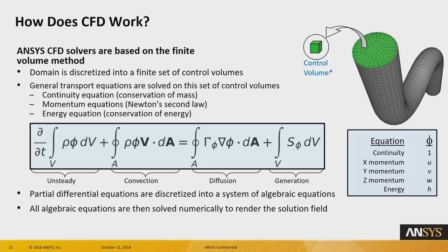What happens in the background when you solve CFD is that the partial differential equations are discretized into a nonlinear system of algebraic equations, and at the same time, the space where we are looking at the fluid flow is split into small control volumes.